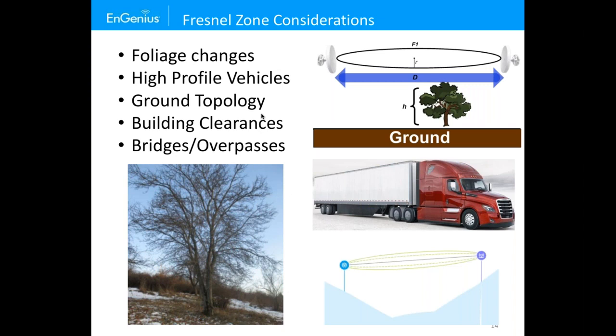High profile vehicles, you're also going to be impacting your RF signal. For example, I had a customer that had gas pumps on the far end of his gas station, and he was servicing semi-trucks, and he had his antennas mounted about 6 feet above the ground. And that was good for cars or for SUVs, but for semi-trucks, they could be up to 14 feet high, and depending on whether they're carrying metal or if they're insulated trailers that have more insulation in them, they attenuate the signal more. When they would pull in, they actually caused the pumps to no longer operate. So the fix for that was to just move the non-root antennas up into the roof line of whatever easement was atop of that, which was like 20-something feet high, to get above those high-profile vehicles.